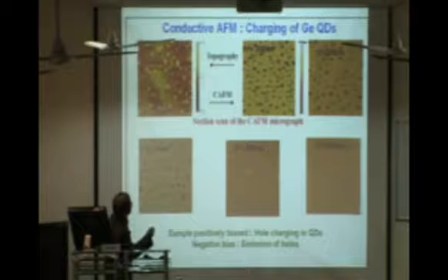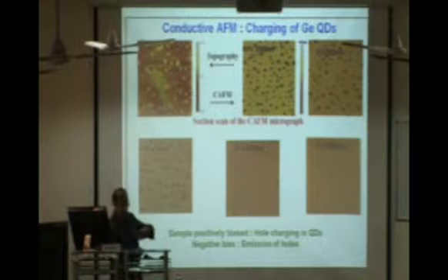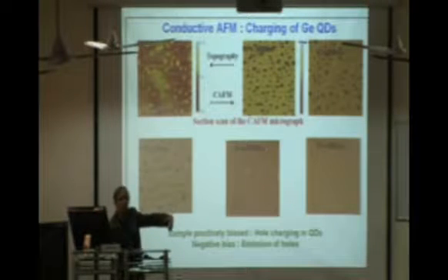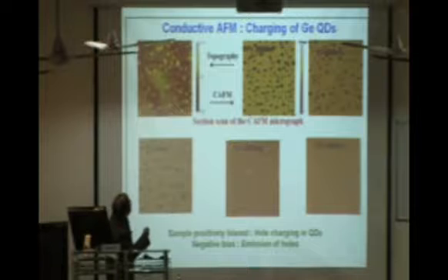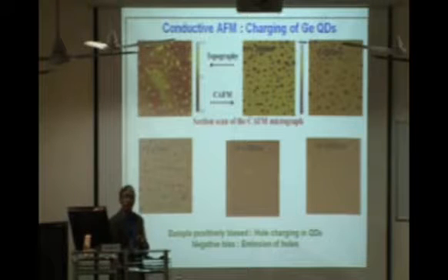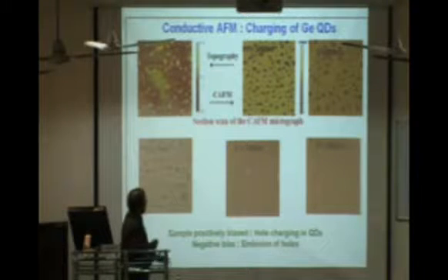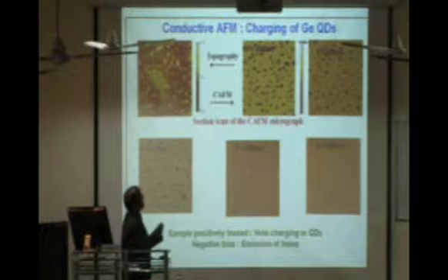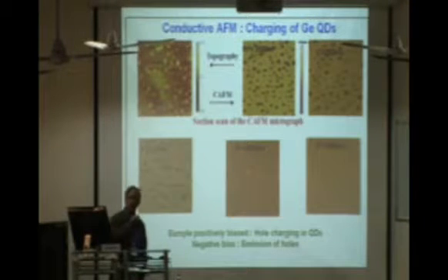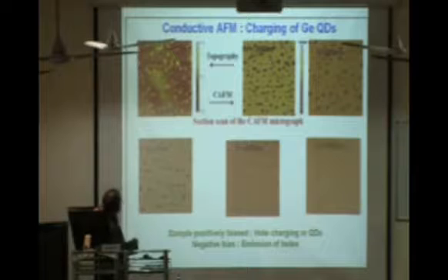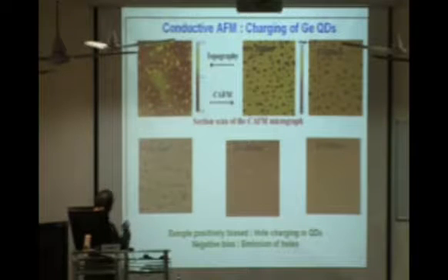So this is the current contrast imaging that shows that charges are transferred to the quantum dots when you apply bias. In this case, these images are taken at V equal to 300 millivolt, 500 millivolt. Our substrate was p-type, and as I said, this germanium quantum dot has a quantization energy level for the holes. So if you have a positive bias on the substrate, these holes are injected into the quantum dots and they charge themselves. And if you keep it, normally it is not removed. It can only be removed even if you take out the bias and do a 0 volt imaging.